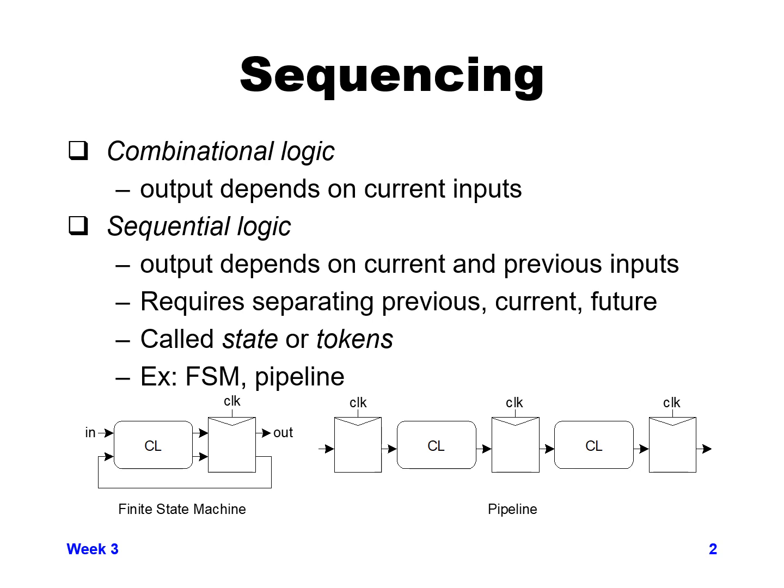There's also something called a finite state machine, where you can have the output of a set of logic feed back to the combinational logic that feeds back to its input, and you wait until it's stable, then you clock it again, you go back through the combinational logic and until you become stable again, then you clock it again, etc. Every time you clock it, based on its own output plus potentially other inputs that might be coming in from other places, you can change the state of the value that you're at. So doing this is called sequencing.